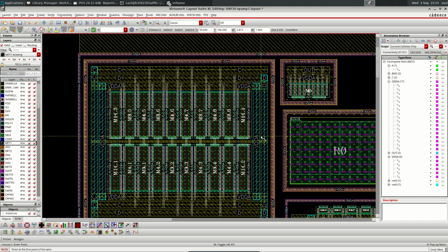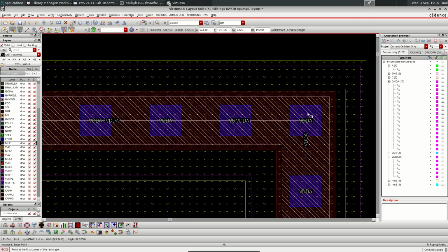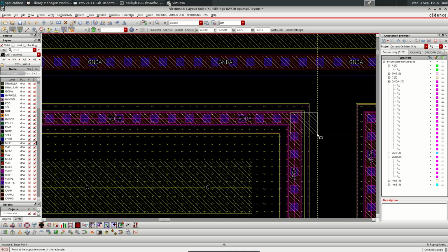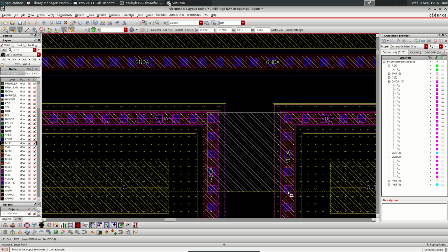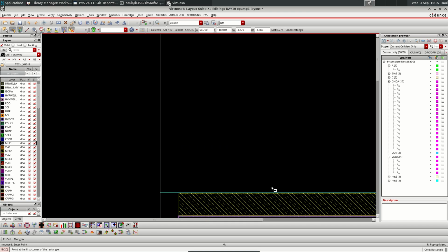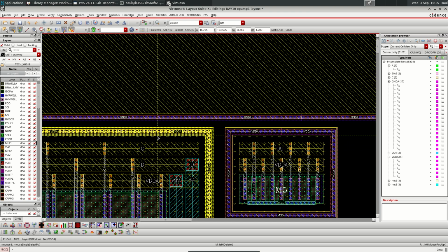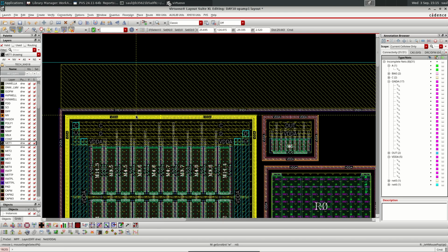Then we need to connect VDD. And we have first the wells. The wells are not really carrying current, but they need a decent connection. I'm going to use a rectangle here for these ones. Let's see, like this. Actually, it is not a good idea to do it like this for now. Let's try to bring it from there. We have VDD on the top that is large.